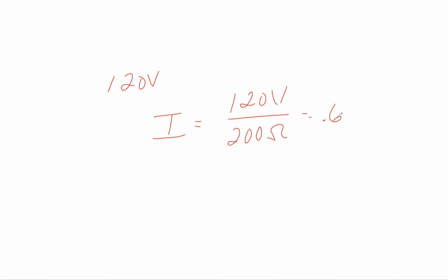So if you're standing in a bathtub and you only are giving up that much resistance, you're dying, because look at your amps and remember the chart I just told you. Anything over 0.07 could kill you. So 0.6 amps is definitely going to kill you. Keep that in mind. That's why there's a joke, but not really, about being wet. You don't want to touch a switch that has water on it, stuff like that.